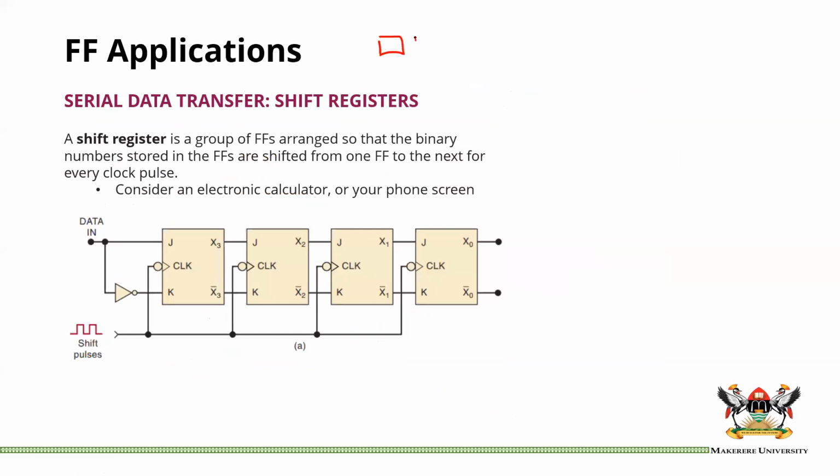If you have your flip-flops, and so on, if I have information here, say a 1, and I want to transfer it to this, I need to give 1, 2, 3, 4, 5 clock pulses, because the first clock pulse, it will come here. The second clock pulse, it will come here. The third clock pulse here. The fourth there, and the fifth there.